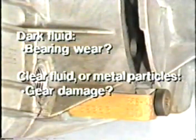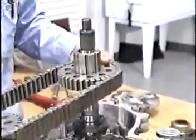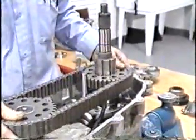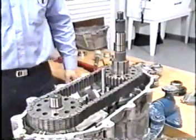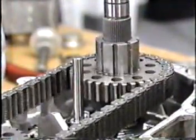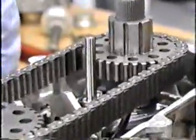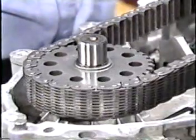Be sure to check the fluid for fine metal particles, as this could be a sign of gear damage. For a noise that occurs only in four-wheel drive, the chain is a very likely suspect, since it's always turning when the transfer case is in four-wheel drive. A stretched or damaged chain would make noise anytime the front output shaft turns. We'll look more closely at transfer cases in the final segment of this tape.